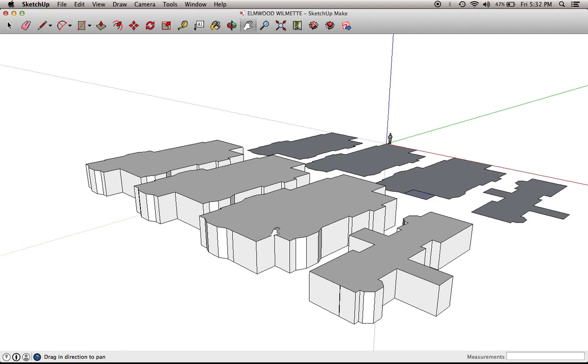It's moving along the axes. I could do it again right now. Take this right here, move up along the blue axis, and it'll tell me again when it's on the blue axis, and I just simply lock it in with the shift button and tell it how high I want that to be. 9 feet, and then I can simply keep on drawing, and I want to make sure that I'm in the right axis all the time. So I might just come around again, up, blue axis, 9 feet, bam.